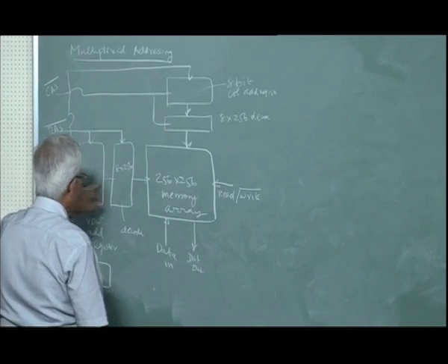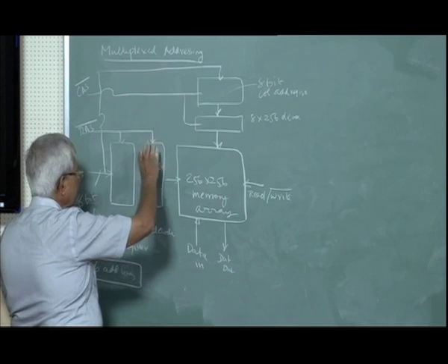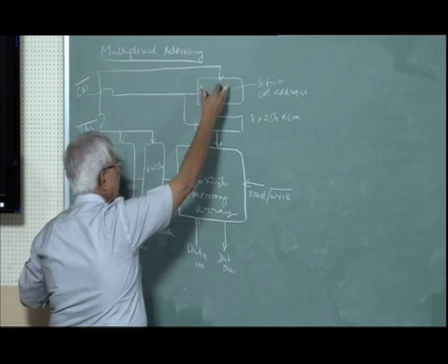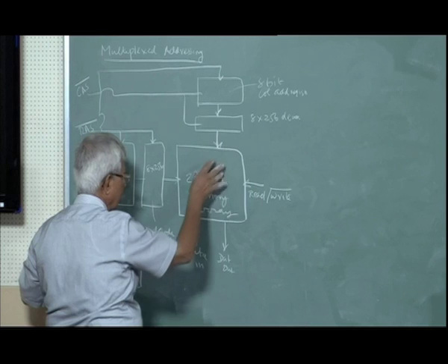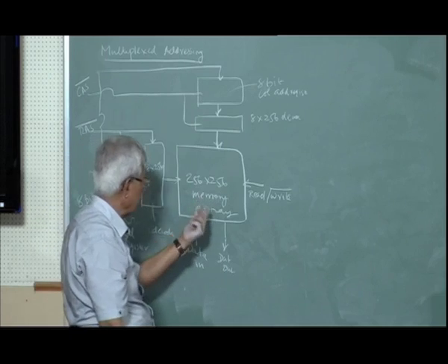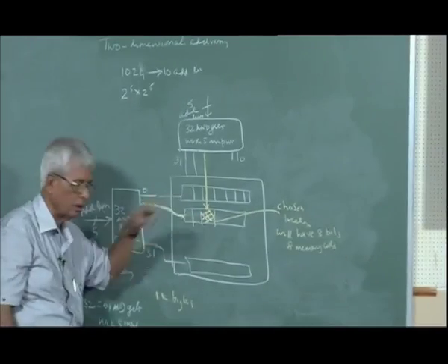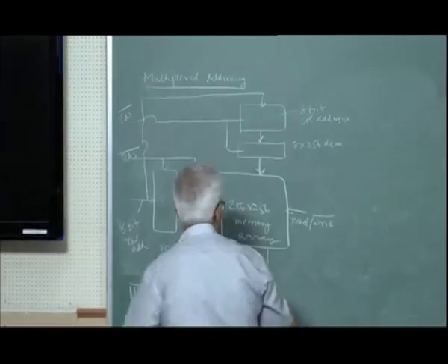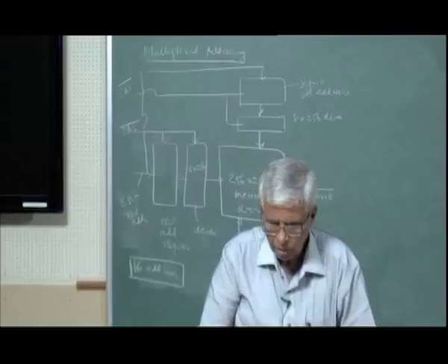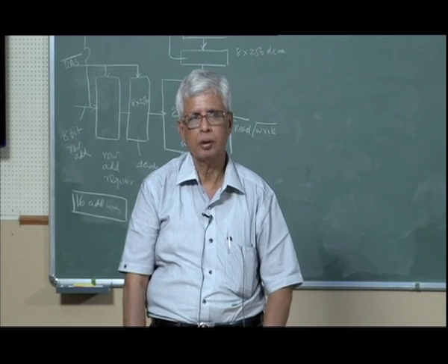First you give the 8-bit address corresponding to the rows. Using the row address register, you store it, decode it and apply it here. Then the same lines we will use to give the column address, decode it, and then together they will be applied here, so that which row and which column is selected, and that is either read or write. Each of these rows will have multiple bits as we did here. All the bits, 8 bits, can be 32 bits, 16 bits, and read write is required. So there are so many devices, so many types, or so many ways of addressing memories, decoding them and using them.